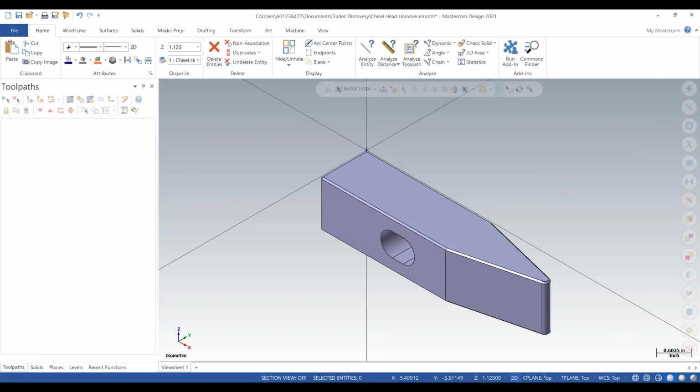And now if I wanted to measure or you see where my top face is, I will click on Z and click one of the points on the top face here. And our Z here should read 0. If we are seeing some other numbers, that means our Z face is not translated properly. Right. So at this point, our XY is translated to that corner, to the back top corner, and our Z has also been established at the top face.